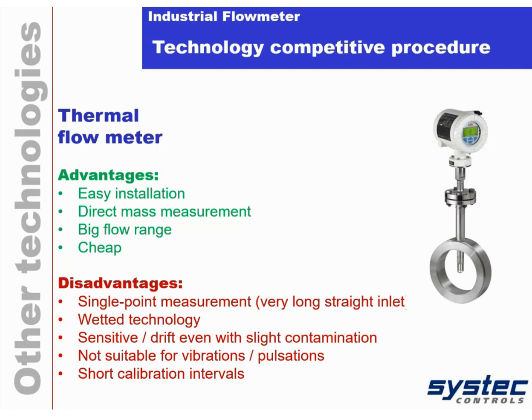In the automotive industries, they are widely used as a reference flow meter for engine test beds. Recalibration interval in the automotive industries is between 3 and 12 months. On good test beds, they recalibrate them within 3 months. So every 3 months, they ship them back to the manufacturer and put a second one in, which is pretty expensive.